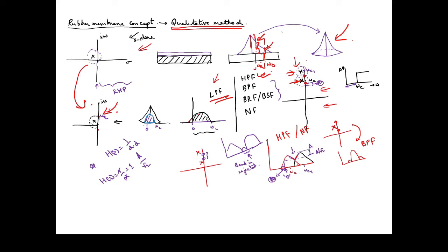Suppose you want to design a band pass filter. Same thing, we have applied two poles over here, band pass. Above one of the poles we will be placing a 0, beneath this we will be placing another 0. So it will be giving us a band pass, because over here the amplitude will be quite low, and suddenly from this 0 there will be an increase in the amplitude level, and then again it will come down to 0 over there.